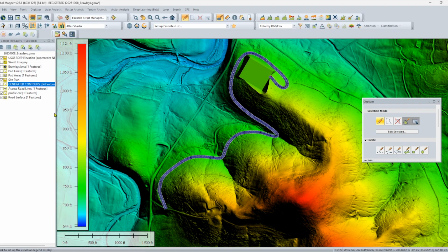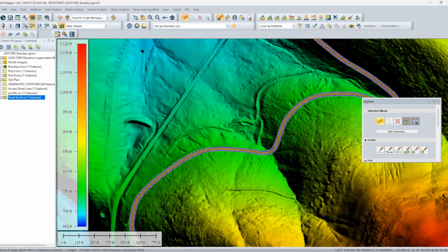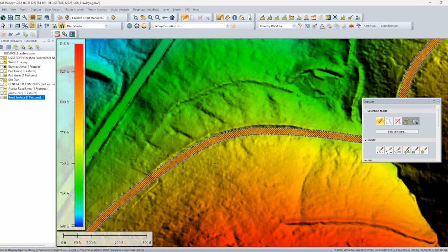Now, I know what you're thinking. We went through all that hassle of exporting the data, running the macro, and re-importing it just to assign elevations to the road. But what if we didn't do that? What if we just took the raw line work, added elevation straight from the DEM, and tried to create the road design right away? Let's find out. I'll show you 2 wrong ways, basically what won't work, so you can see why those extra steps matter before generating a proper terrain surface.